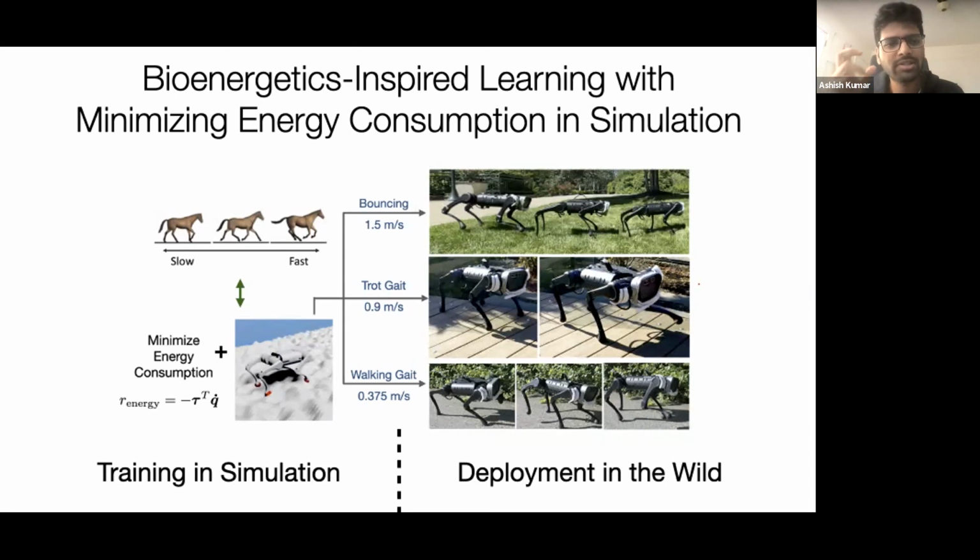So in legged robotics, the biggest problem are the motors. Every time the robot walks and the leg hits the ground, the motor goes through some amount of impact. We would want to minimize that impact, and vision can let us do that, because if the robot has to climb stairs by hitting the stairs first every single time, that is going to shorten the life of the robot. So I am all in favor of having a vision camera. When I said no vision, I was just trying to mention that this work has no vision. But yes, I'm completely in agreement with you.